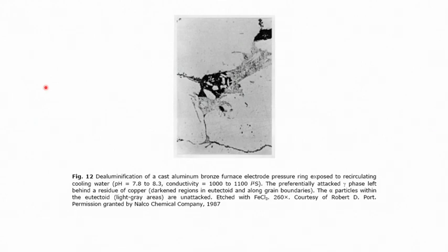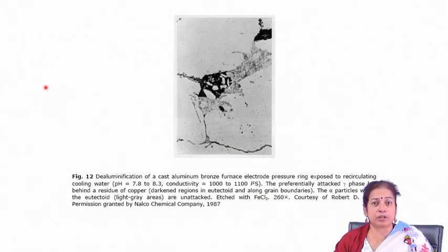So, you will find that there is microgalvanic cell formation between the grain boundary regions and grain regions, and also the adjacent grain boundary regions get depleted in chromium. So, the problem starts at the adjacent boundary regions, and after the corrosion is over, you will find that failure starts from the adjacent boundary regions rather than the grain boundaries. On the other hand, if the grain boundary possesses a lot of active elements, it will be electrochemically more prone to corrosion as compared to the grains. There also you will find that grain boundary attack will be more than that of grain bodies, but there the attack is through the grain boundaries.